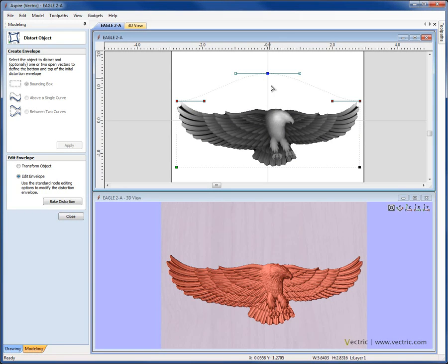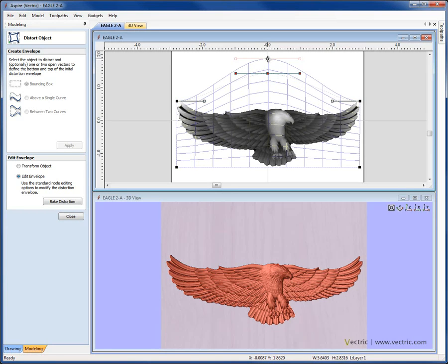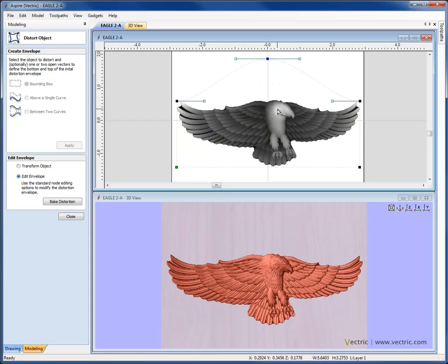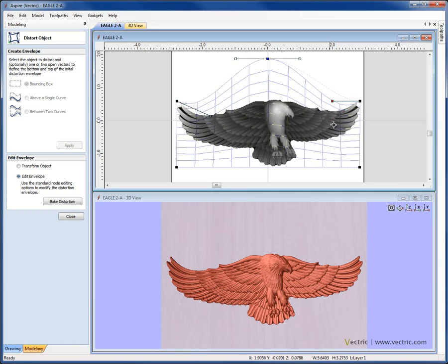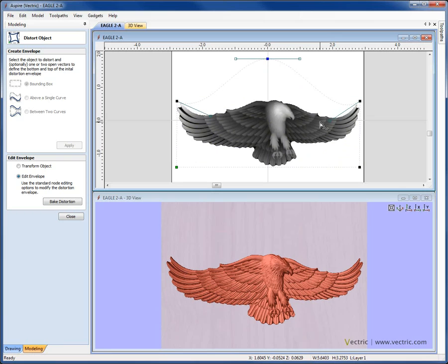And this is an extremely powerful way for me to edit a component shape. So you can see there we've completely changed the way the wings and the body looks now in order to have it so that they're curling up and out the shoulder and down towards the wingtip. We could even accentuate that curvature by dragging these control handles down. So there's one example where we've taken a very freeform shape and used some of the power of the bounding box distortion tool.